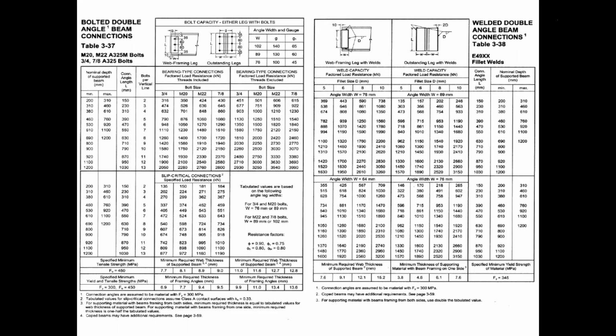3. On this side, you might not see it, but the bolt is going right across here like this to be able to connect it. You understand that this is where this bolt is going right across. So here the bolts have double shear, and here the bolts have single shear. Therefore, it's the number of shear planes. Because they have exactly the same number of shear planes, I had the same VR.